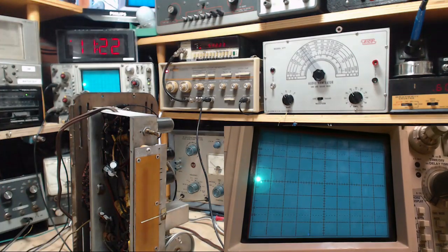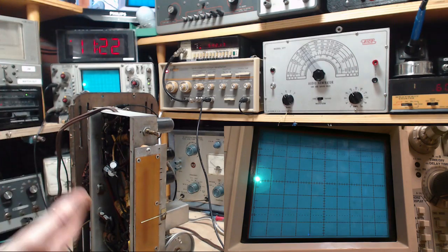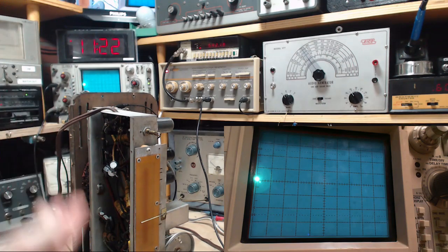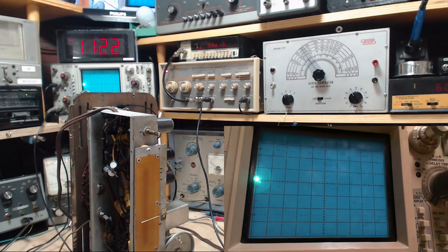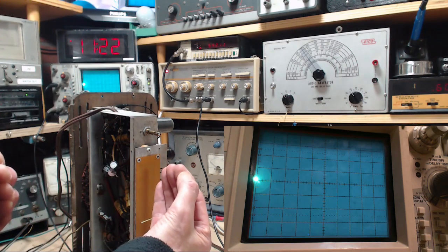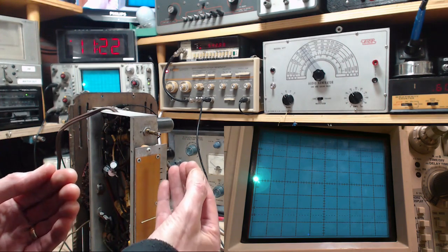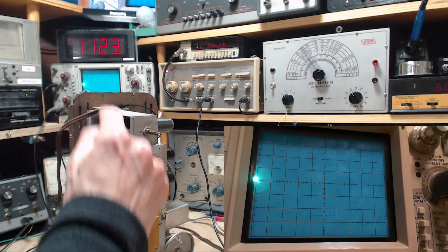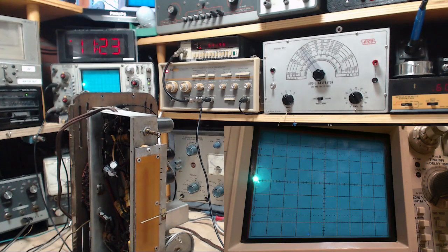There, that's a way to stop that sound. So I've got the sweep generator sweeping through the entire receptive band of the radio, the whole AM band. At some point it crosses where the radio is tuned. At that point a signal comes out of the detector, a DC signal if you like, briefly, because the signal is not sitting there, it's going by. So a DC voltage is created, but it doesn't have too much time before the input frequency is changed and it's going to come back down again. And that's what's giving you the curve shape there.